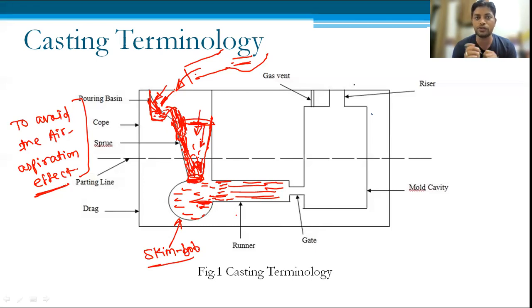But if we are melting alloys and using the molten alloy, there is a possibility that the high density particles, in this horizontal passage where the metal is in liquid form, will try to sediment at the bottom part of the runner, and the low density particles will try to move towards the upside.